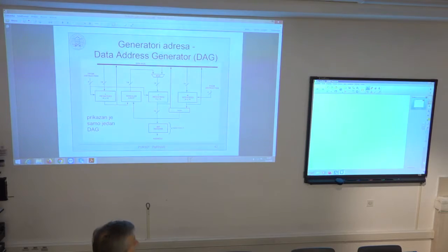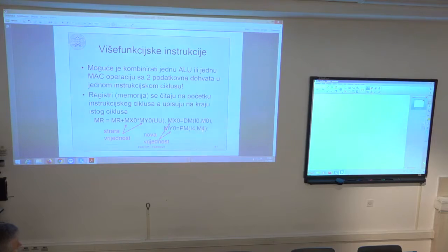So, for example, if M0 were -1, and I do the fetch with I0, comma, M0, then in this case it will decrement I0 by 1. So you simply store the desired modification values in this set of M registers and invoke one of those registers after performing the fetch operation by simply having this comma M0. Okay?